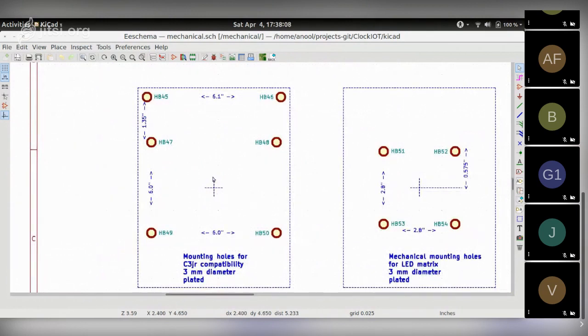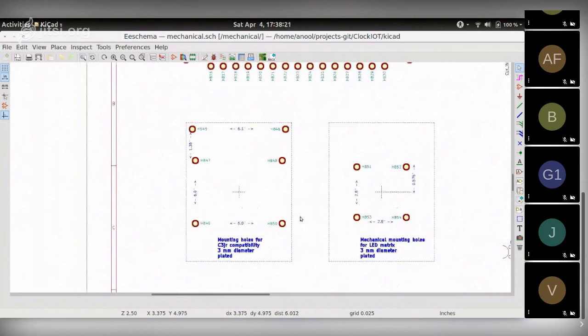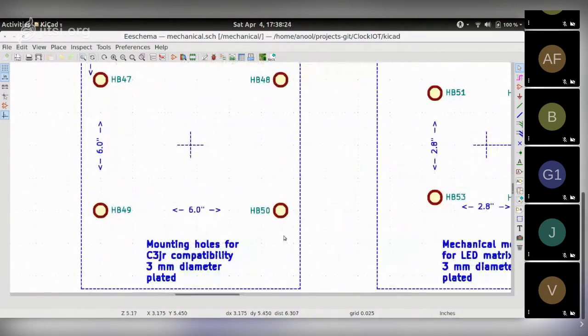So I know around the center mark of the crosshair, the vertical spacing is 3 inch on each side, 3 inch horizontally as well, and so on. But yeah, these were cosmetic, but I know exactly where each hole needs to be. Quite often with mounting holes, it becomes easier to get confused about which hole is at which corner of your PCB, because they could be, let's say, H1, H2, H3, H4, but it helps to know in which corner they are located: northeast, northwest, southeast, southwest, and so on. Yeah, it's a nice way to do it.